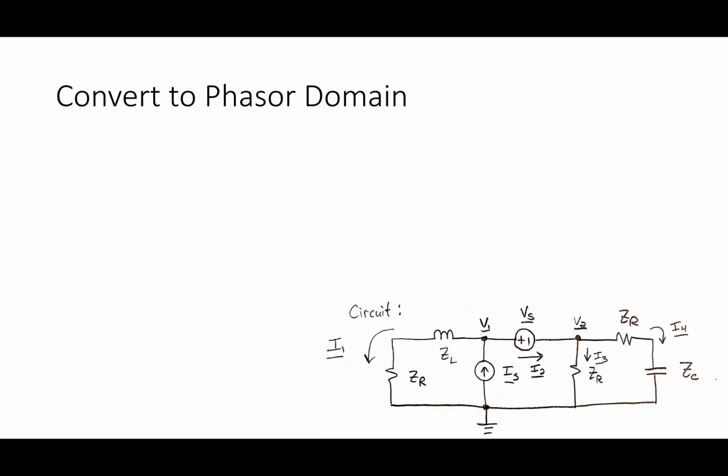For me, where I start with this is, as I said, I like to define all my currents and stuff. So what I do here is I say, all right, I'm going to define a voltage across that series combination, because technically what I have here is one impedance, right? I put this all in the phasor domain, but I should be able to write it like this. Here's V sub S. I'll call this R. It might be a little easier to view it like this.